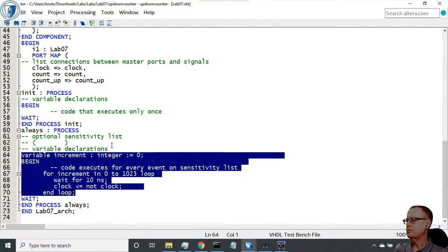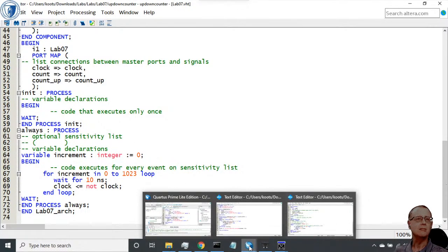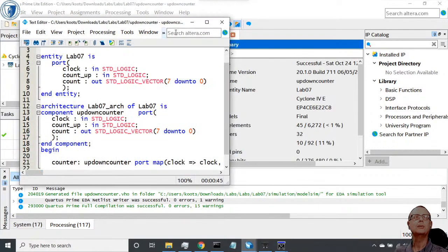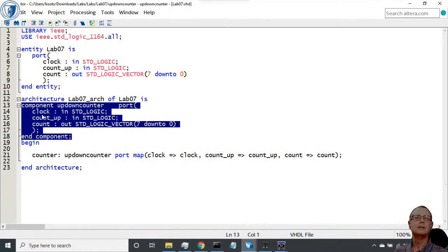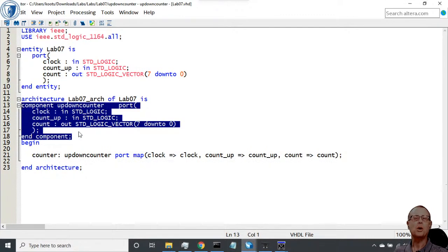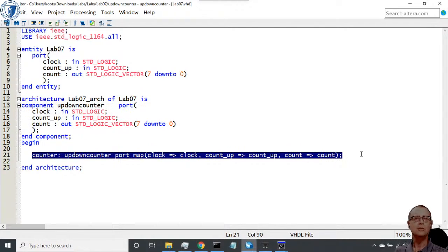All right, and how about the VHD for Lab 7 as well? The VHD for Lab 7. We can have a look at that. Is that it there? That's it there. So let's detach that window as well. Right, so here, it's line 21 there. So that is instantiating a version of the up-down counter, right? We define the component that we're looking for here, and to actually instantiate it, we need to do that port map statement.